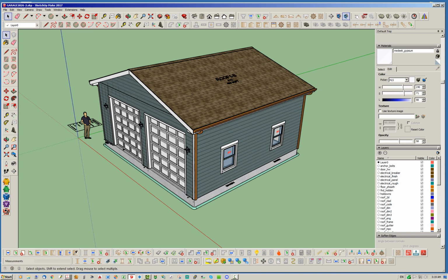So the problem there is that you're kind of left to your own devices. I mean, not to say that it's that much of a problem. It's just a matter of you need to be familiar enough with layout, create your scenes here in SketchUp, and then take your scenes and drop them. Your elevation views, your floor plans, your sections, all that's good stuff, and create your applicable scenes. And then from there, you've got your construction documents.